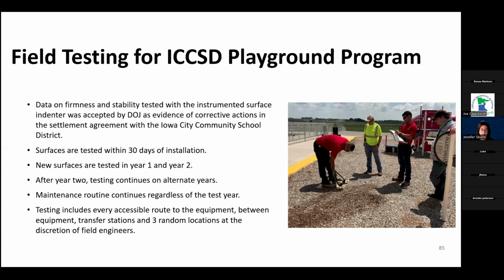In the first 2 years of testing, they went from barely an 80% pass rate on the values that they had adopted to more than a 98% pass rate by the end of the second year, because they were able to adopt this compacting protocol where they compacted the surface in 3 different directions. They had it installed and layered, watered, compacted, and they went in the 3 different directions and had a much greater success rate based on the data that they were able to collect.